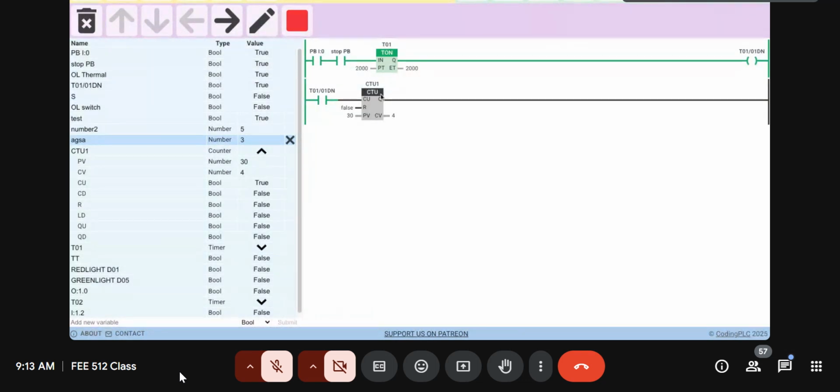So you realize that when you set the timer on, if you just have one count, you will have to have that reset and preset system to make the counter continuously count within the preset value of the counter.